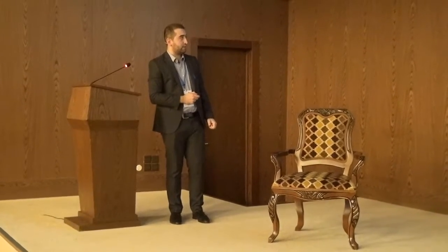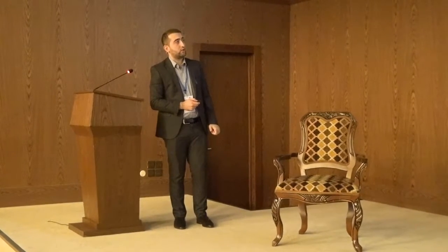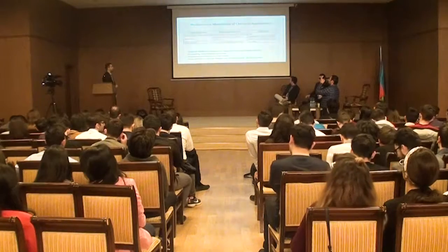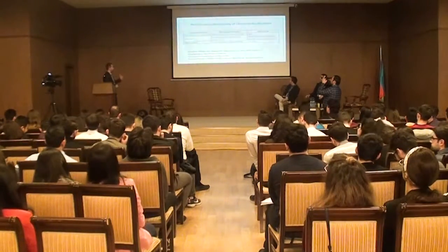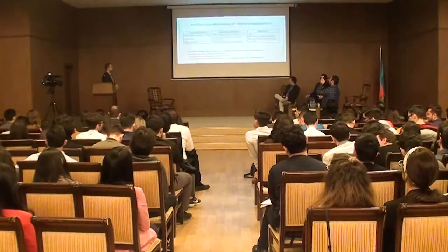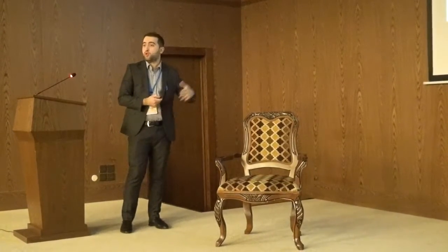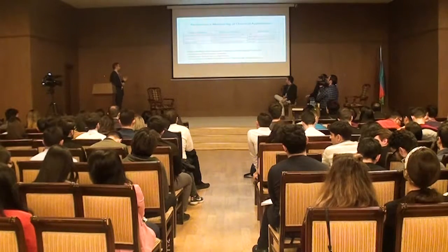For the chemical application number 2, antifoam, the monitoring parameter is liquid carryover to the gas outlet. We keep records of the gas analysis, where we also look for liquids in that gas, to make sure that we are not foaming in the system. And it needs to be below the process-specific limit, which is defined by the project team when they design the system. And it also affects, as I said in the previous slide, the level control. That's why we need to monitor the level control. We need to be very careful when we control the level, because we don't want any high alarm due to foaming. So you have to be very sure that you are not foaming the system and your chemical application is in place, and you keep dosing your chemical to avoid foaming in the separator.